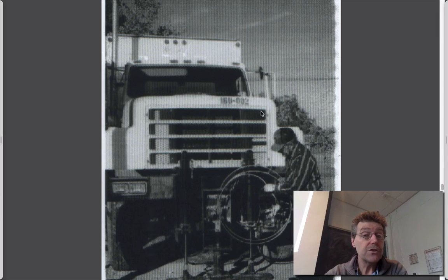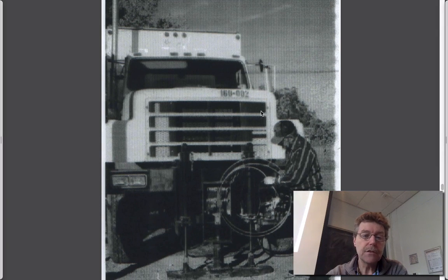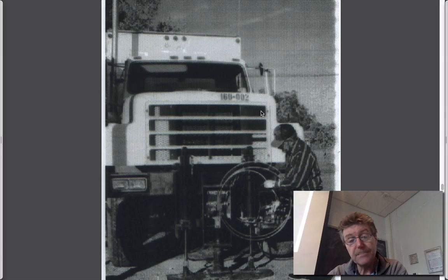And you might want to measure pore pressures that you generate at the tip or that were present in place at the tip. And so these methods are sometimes referred to as cone penetrometer tests. They're now also marketed by companies like Geoprobe as direct push methods. And the basic idea is you physically push a rod which has an end area of 10 square centimeters. So I think it's 1.25 inches diameter. You could work it out.